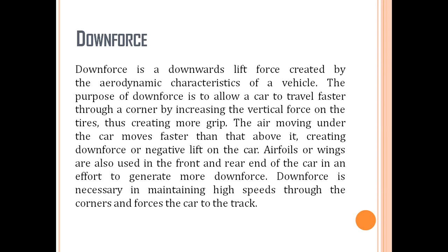Okay, so thus creating the downforce. If the velocity is increased, it means the pressure will be much lower there. So the air under the vehicle will be moving at a very fast rate, so that it decreases the pressure. When it decreases the pressure, it means it increases the downforce or negative lift, so that no wheels of the vehicle will be lifted into the air.